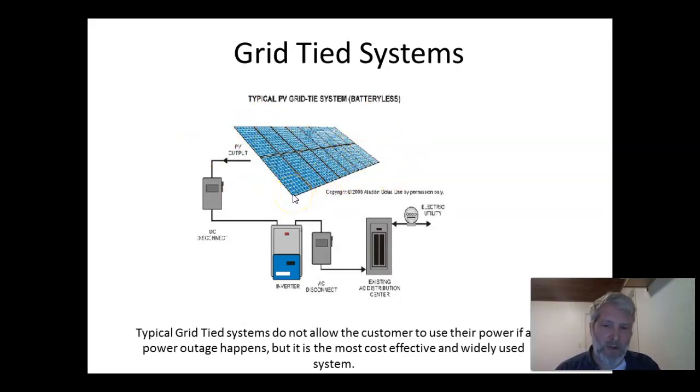We'll go into this more when we go into the system components next week. But each one of these cells is roughly about half a volt in monocrystalline and polycrystalline, and they're tied in series with each other. So a 60 cell system would roughly have around 30 volts, and a 72 cell system would have around 36 volts. The open circuit voltage would be 0.6, so whatever 0.6 times 72 or 60 would be, that's your open circuit voltage for those.